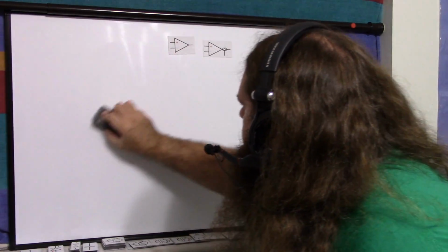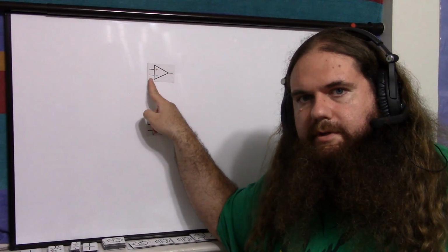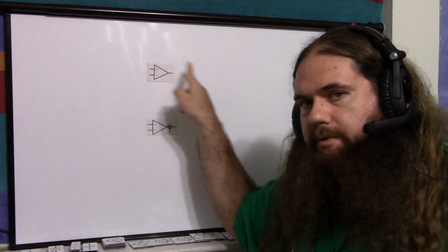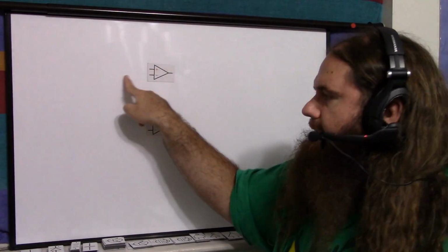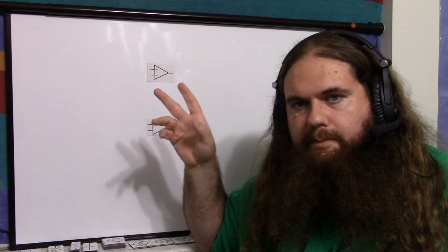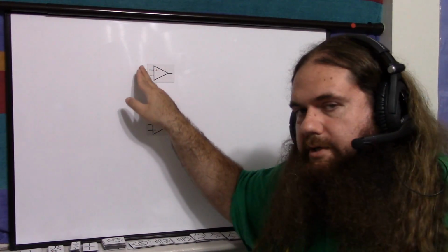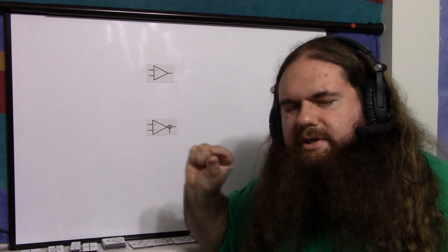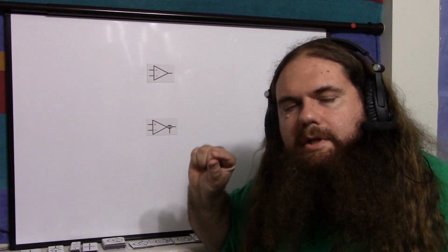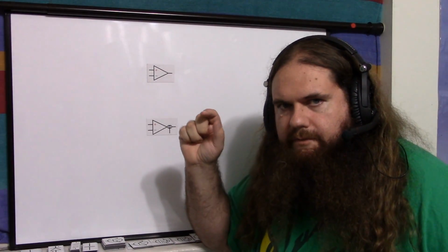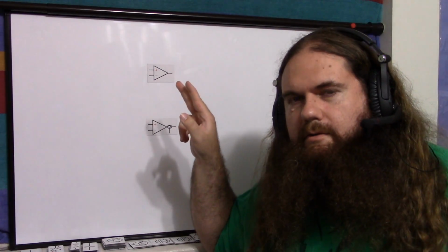So what are the inputs of this OTA? How does it work? So the op amp takes a differential input voltage, and you usually use it in closed loop formation or a closed loop configuration. That means the output feeds back into the input, and you configure it with resistors optionally. And what happens is the chip, the feedback, causes the differential input to go near to zero, just a hair above or below zero. So the differential input ends up being millivolts, just a handful of millivolts. And the crazy gain, 100,000 or more, causes this big ol' voltage output.